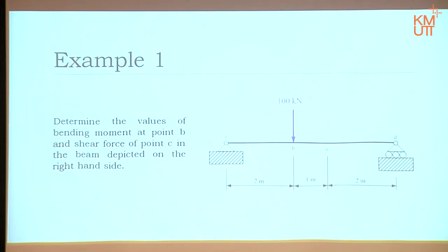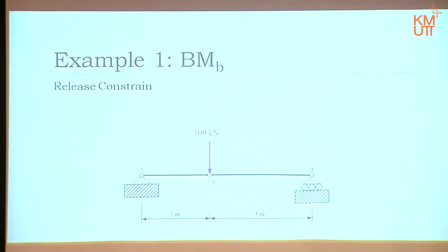at point C. If you remember the first half, the strength of the virtual work is that you don't need to calculate anything else. You can calculate the value you want to know immediately. This will be the same case here. Meaning we don't need any reaction at all. We can go straight to the bending moment equation and shear force equation and calculate the shear force. Okay? Let's trace the steps.